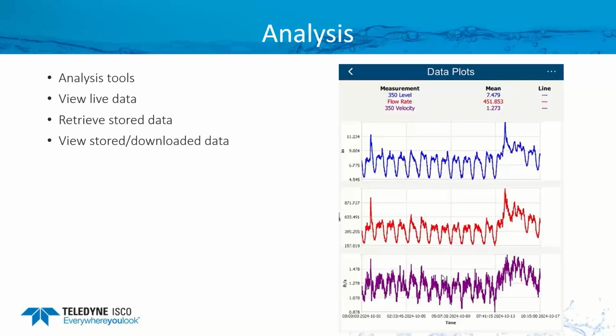You want to make sure everything looks good before you leave. I can download last week's data, so I can pop it in there and make sure, yep, everything's been working okay, or maybe I've got some ragging going on. As of the last three days or so, I've got ragging going on, so I need to get down there and clean that sensor. But it does allow you to see the data that's been stored in the meter that you downloaded on your device, in this case, your laptop, and you can see how that signal looks.